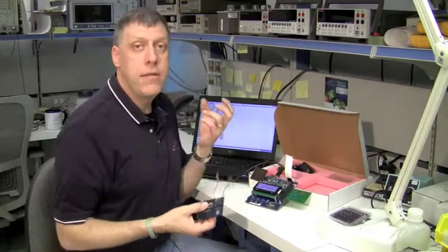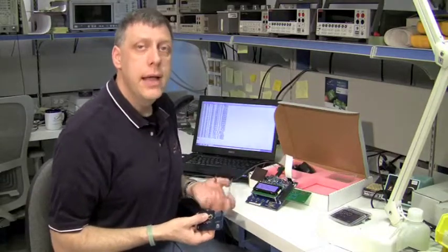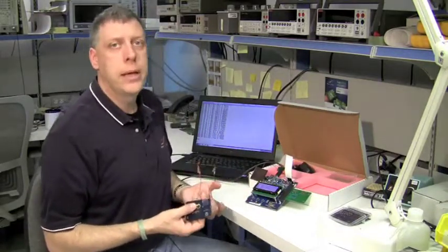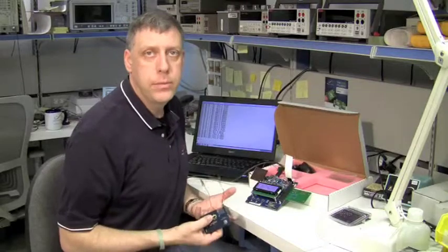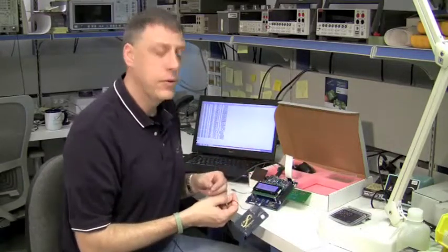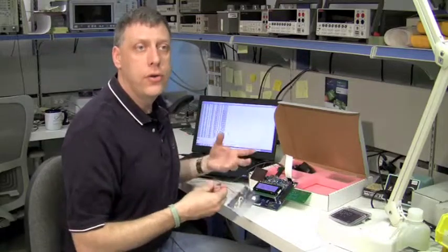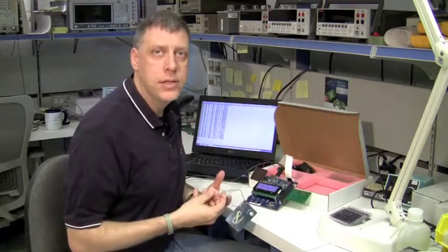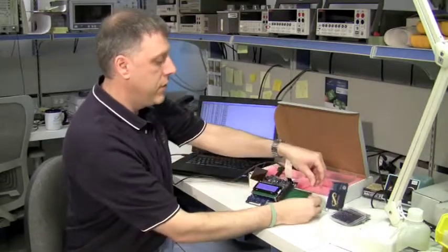It means, is the amount of energy you're getting in greater than the amount of energy that you're putting out to your application? If you don't have sufficient energy coming in, what you're going to find is that your battery or your power source or power storage unit, whatever you're using, is not going to be sufficient to run your application indefinitely. So if you have a wireless sensor module or wireless sensor node out there, for example, and you have a solar panel on it, you need to make sure that you're getting enough energy over time while you're operating the device to make sure that you never run out of power and then lose the function of your end device.